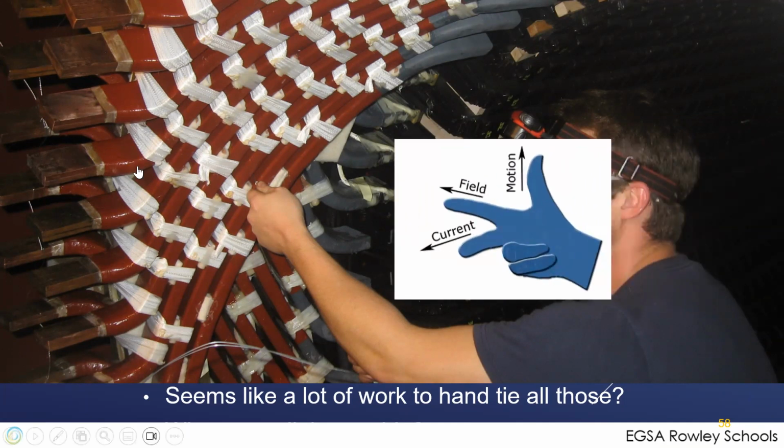So we want to keep the windings from being disturbed, physically pulling themselves apart, breaking a connection, or moving and coming in contact with the rotor because they were moved in the fault.